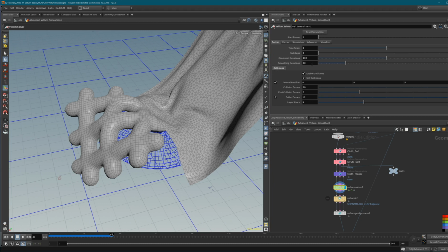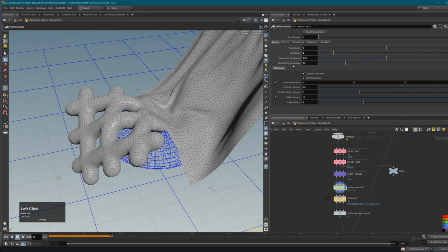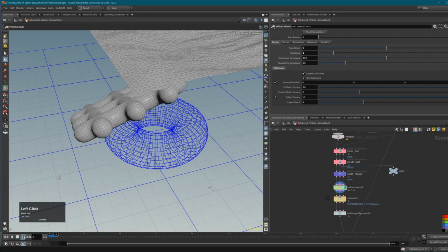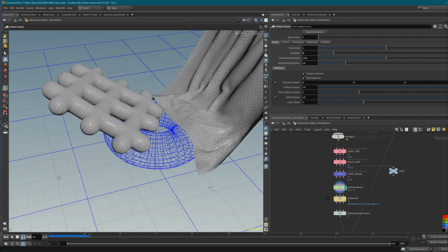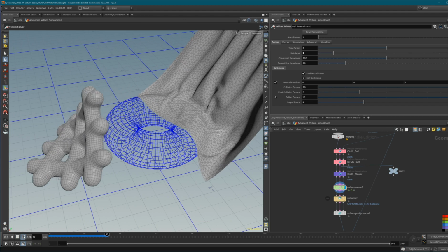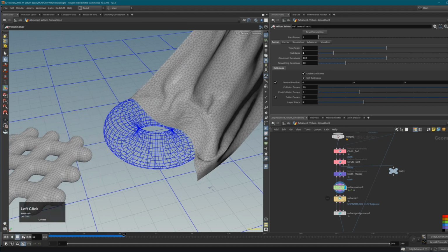And then there are smoothing iterations that take out a little bit of energy of this simulation. And if I, for example, now increase the substeps, substeps means it does it one time per frame. If I set this to 2, now it will run these constraint iterations 2 times per substep. So now we actually have 400 constraint iterations per frame. And this sometimes resolves bad intersections and will also change the behavior of our cloth. So this is also very important to know.